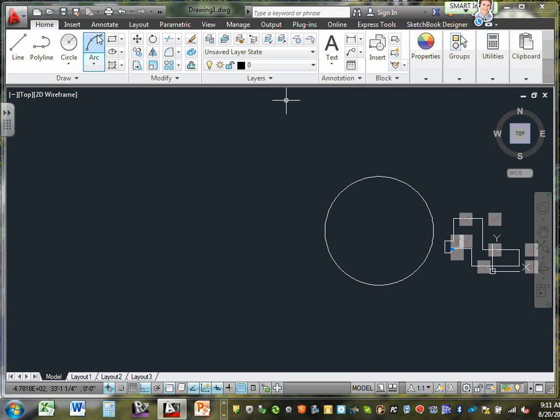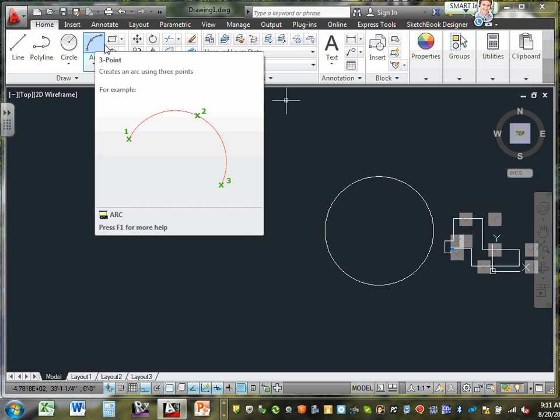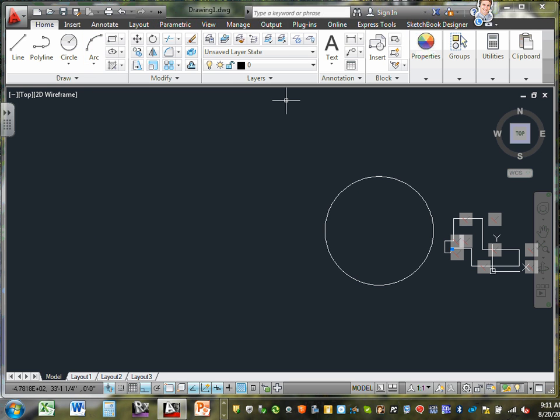that's what I want. I want you to pay attention to the arc though. The arc is a big deal. Let me know when you're ready for an arc. So let's go an arc. The reason why the arc is good, guys, is that when we have multiple receptacles, we have to connect them with an arc. Loop them. So click on an arc. You pick the first receptacle.